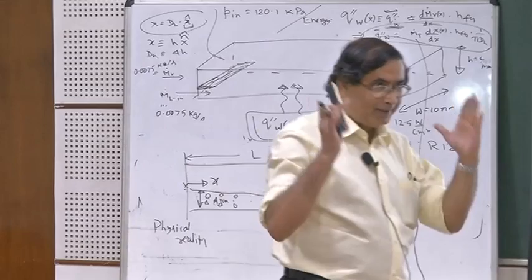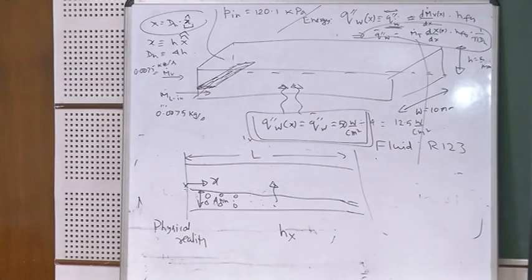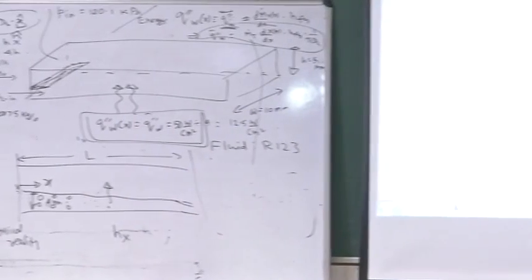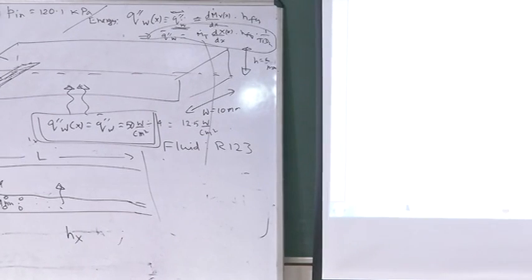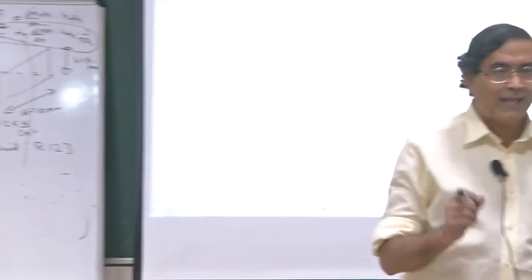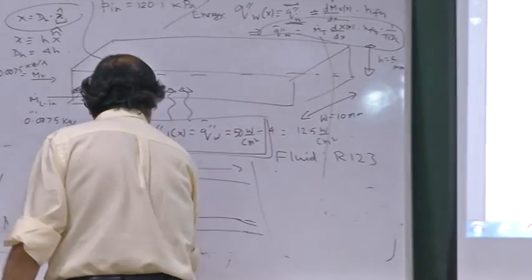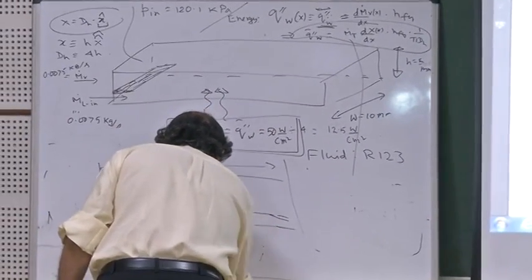Hypothetically, it's a mental imagination, with no nucleation. If you are able to achieve the same interface configuration, it will happen for a certain heat flux or a certain wall temperature, which won't be the same as in the real case. But you hypothetically find that thermal boundary condition for which you have the same inlet, outlet and liquid-vapor interface, and when you find this, the hypothetical situation, same delta x,